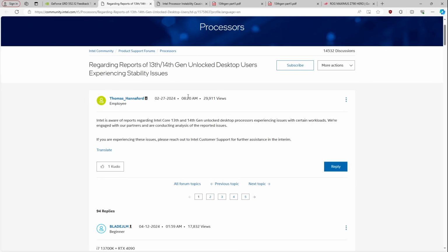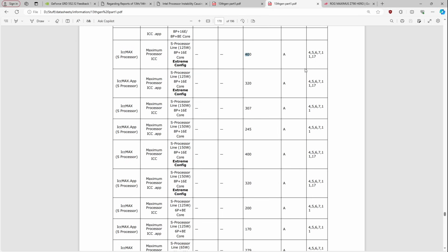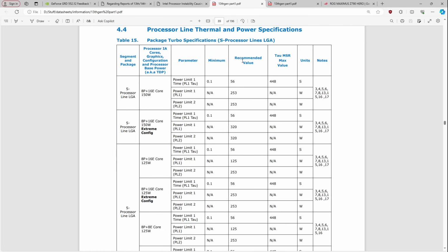Now, the last thing I want to address is that there have also been rumors of the 13th gen, 14th gen CPUs degrading because of the auto settings being complete insanity. I find that very hard to believe, because while Intel may be kind of sloppy with the power limits, I would really hope that they aren't so sloppy as to set the TJ Max and the VID table in such a way that the CPU degrades at 100% load.